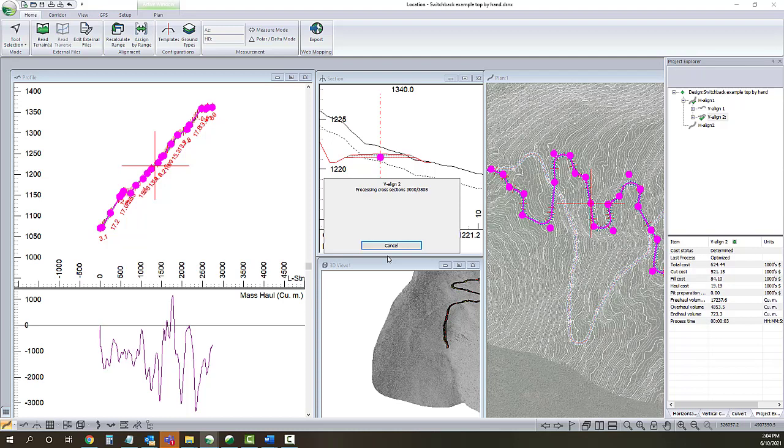We're going to end up with a fairly humpy bumpy road. It's going to be the cheapest option, but our curves are going to be butted right up against us. If we wanted to force tangents between our curves, we could change the setting.